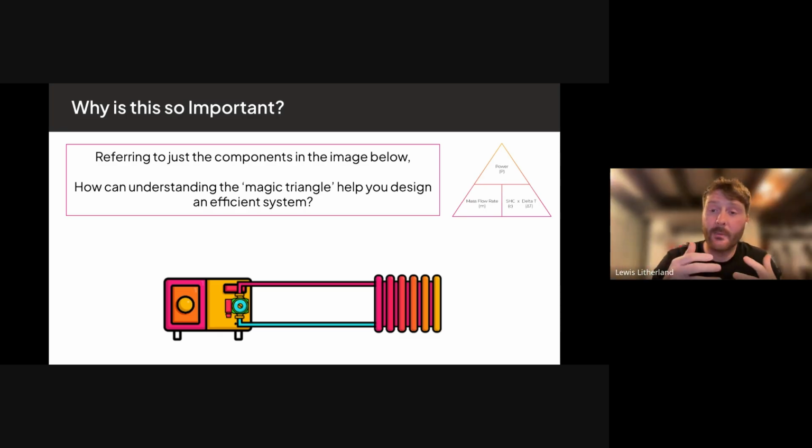So we need to know our mass flow rate so we can choose what pipe size we're going to use. And you can only find out your mass flow rate if you know how much power you're going to be sending down that pipe. This is where the next couple of modules go into pipe sizing, because it's a nice, easy progression, and this is your introduction. Once you know your power, you get your flow rate, and then you ask what size pipe you can use.